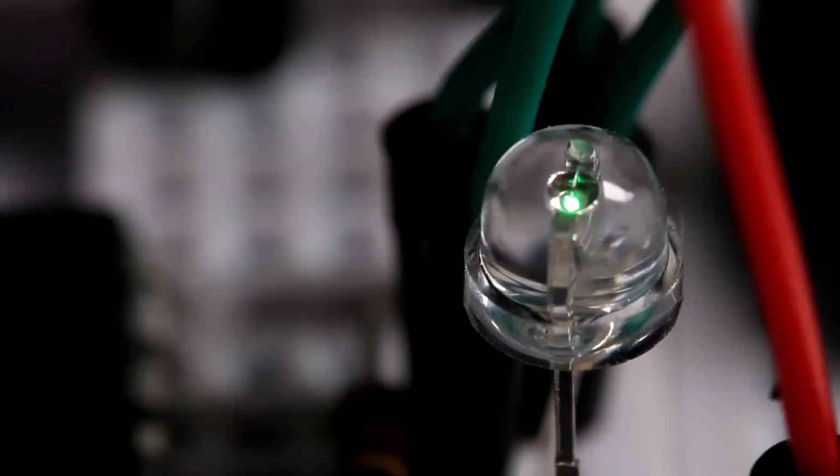In this green lead, the depletion region is formed in the cup-like shape at the top of the dome. The piece of fine wire within the dome joins the cathode and anode, making the p-n junction visible. Each time an electron falls into a hole at the junction, a photon is emitted, and we observe this as green light. Reverse biasing the device widens the depletion region, stopping both current flow and light production.